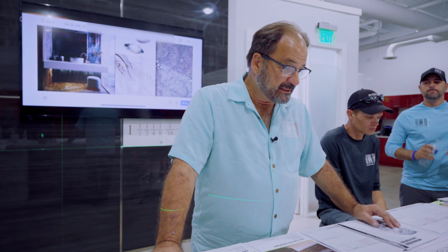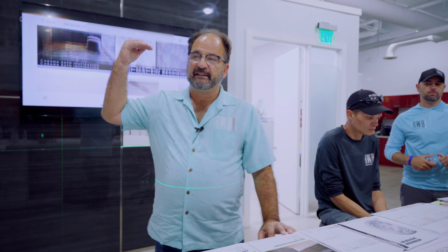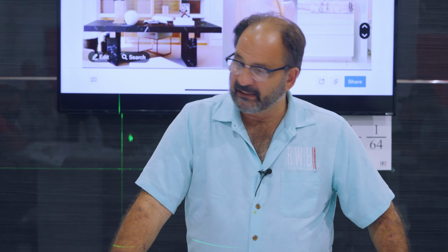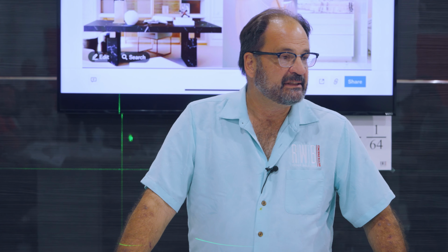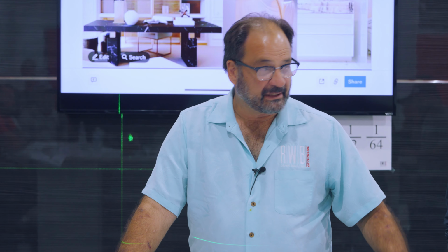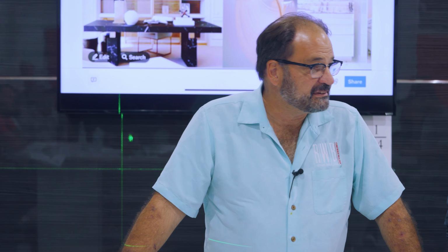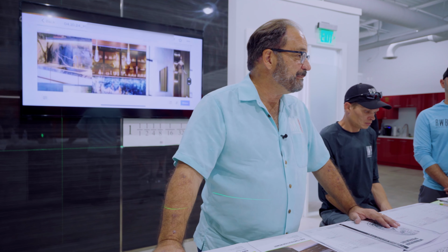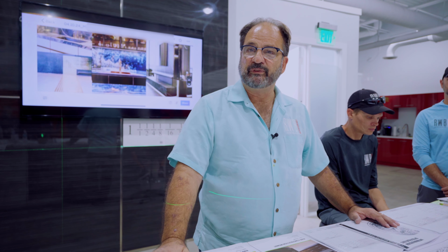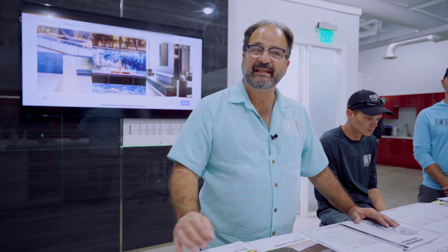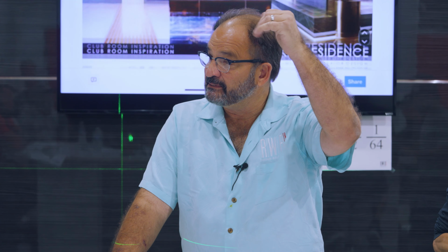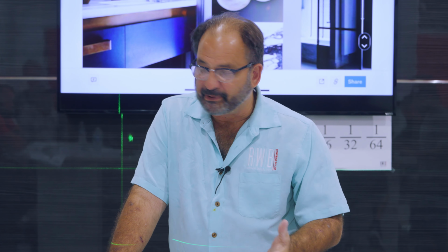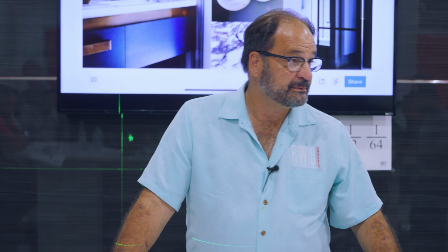Okay? At this job, we had a long drain that had to run across the ceiling and underneath the beam. We wound up adding another line down to the basement or the garage to tie into the main drain line and diverted the pipe from going underneath that beam. That let us pick the ceiling up. You don't know that until you lay the entire thing out. That means not just lay out the floor. It means check your ceiling heights. It means looking at the drawing with the plumber, let him tell you where he's going to go.